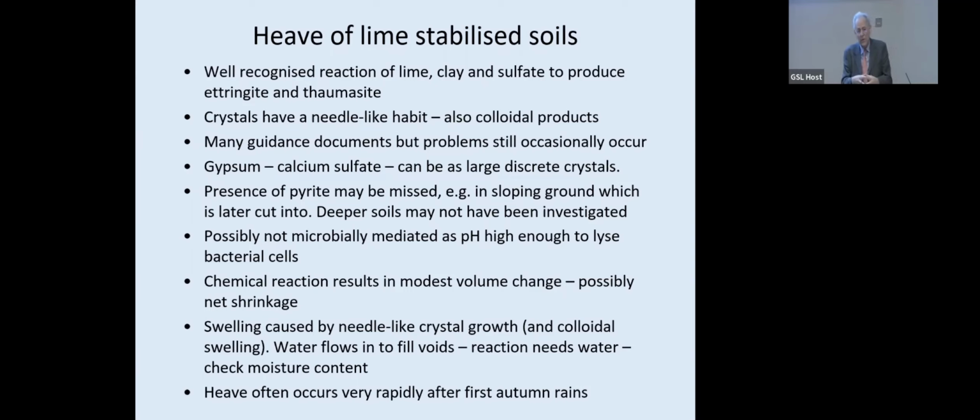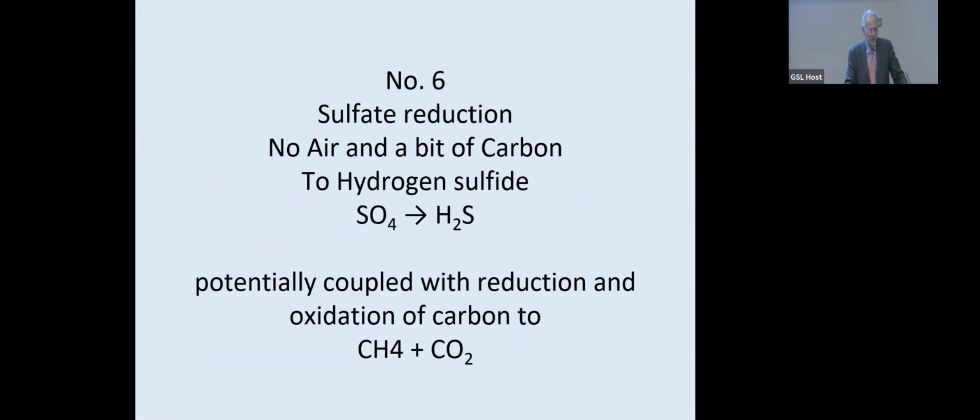So if you want to know whether it's swelled or not, the easiest way is just to measure the moisture content. It gives you a brilliant example. There's no actual need to, and I'm not convinced about the current advice on how to do those tests. Interesting, that heave often occurs after the first autumn rains. We do the lime stabilization over the summer period when it's reasonably dry, get that first bit of rain, boom, and it can almost come up overnight. And the lime stabilized layer can almost double in thickness. These are big movements: 100 mil, 200 mil, 300 mil, not a problem.